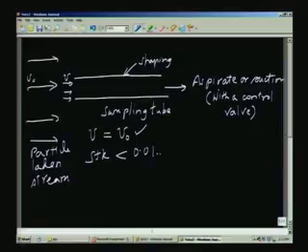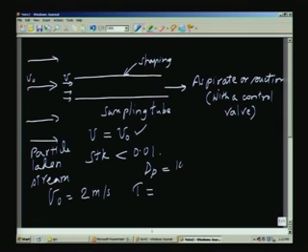In this case, we are given that the velocity u naught is 2 meter per second, and for the 10 micrometer particles, dp equal to 10 micrometers, fairly large size particles, tau is given as 3.11 into 10 to the power of minus 4 second, almost 0.3 millisecond.